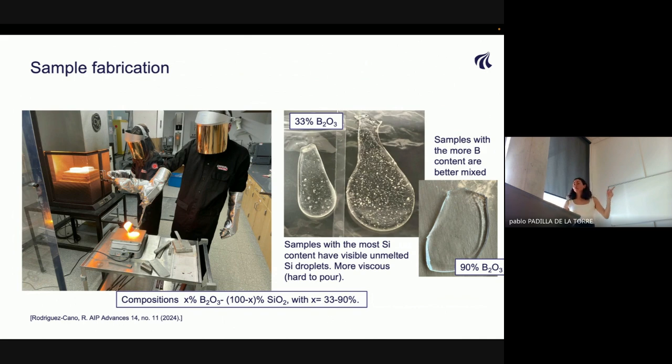So fused silica melts at 1,700 degrees. That is why they don't use fused silica, because it's very expensive to heat to that temperature. But with glass, you add modifiers to lower that melting temperature. So your furnace has to go a bit below, like 1,400 or 1,500. So you just need to find a furnace. Then you also need a crucible. I think the material is rhodium, which is also very expensive, like 20,000. Then you just buy the powders, mix them, and put them in the furnace.